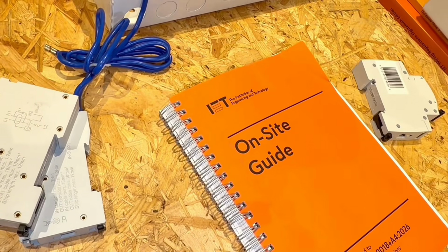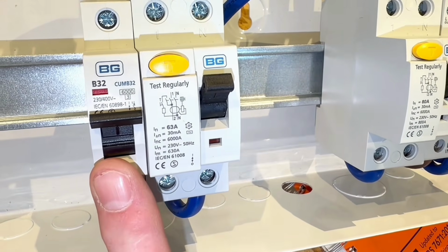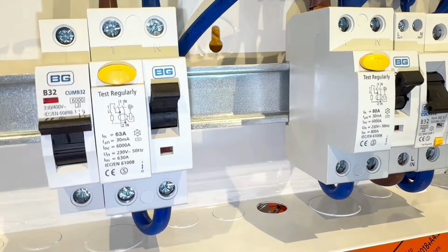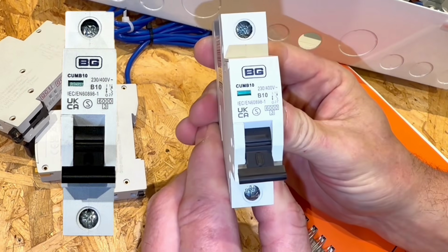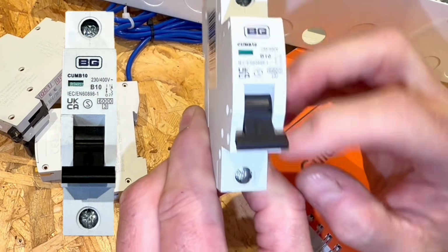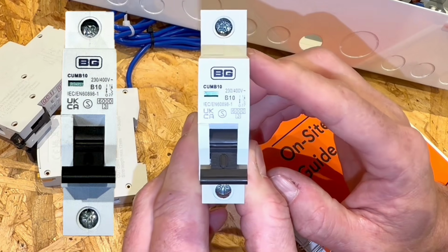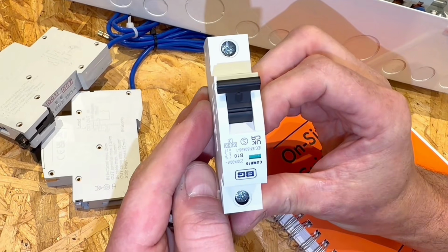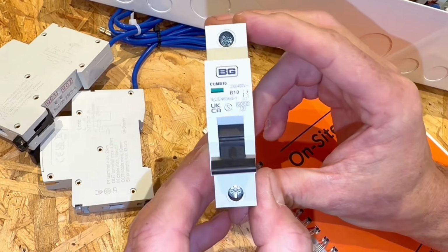However, in between this, we had this style of consumer unit, possibly the split load board, where we had both an RCCB and an MCB. Now, we've got to work out whether these were bi or unidirectional back in the day. Well, let's start first of all by looking at a standard MCB using the knowledge we've just acquired. This MCB here has no markings on the top and no markings on the bottom. Therefore, just have a quick think, this is actually bi-directional. So our standard MCB is bi-directional. If you fiddled it around, you probably could wedge it in upside down. Obviously there's a DIN rail connector here, but it could go either way round. But that is actually a bi-directional device.